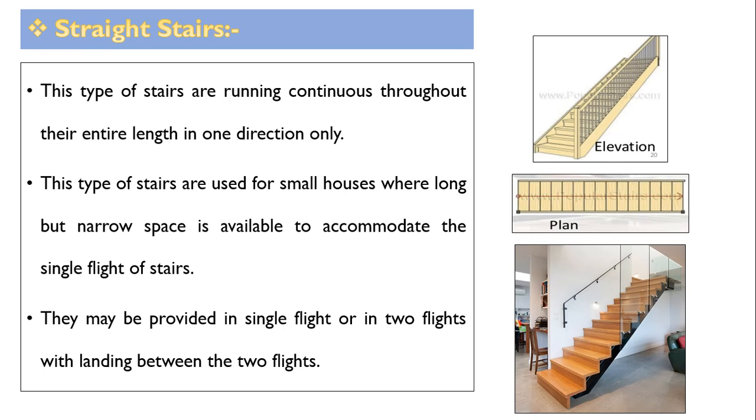They may be provided in single flight or in two flights with landing between the two flights. So in case of this staircase, normally it consists of single flight. Sometimes if the distance between two stories is more, in that case in between two flights additional landing is provided to take the rest. So in that case it is divided into two flights. So this is regarding straight stair.